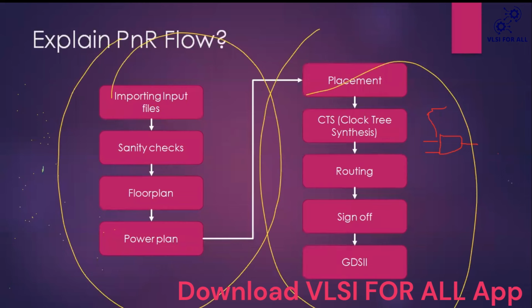After CTS, routing is the stage. During routing, the tool will avoid all the congestion. Congestion means overlapping nets in the same metal layer.